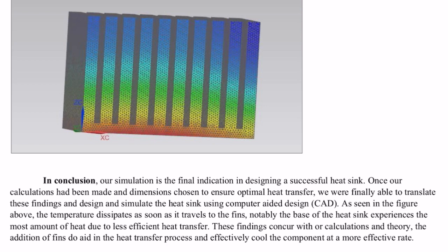With this, we were able to translate these findings and design and then simulate the heatsink using computer-aided design, CAD. That, of course, was done by Esteban, and as he went over, and seen in the figure above, the temperature dissipates as soon as it travels to the fins. Notably, the base of the heatsink experiences the most amount of heat. This is due to the less efficient heat transfer it contains.